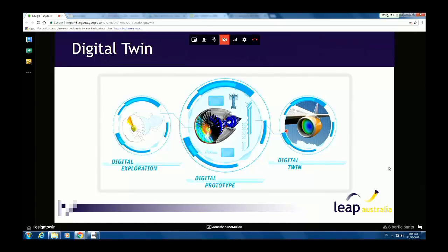Depending on how complicated the digital twin is, it can do things like fatigue calculations. So it will throw a red flag if the vibration is causing the design life of your bearings to drop too far. And so particularly for automotive models now, where the design isn't actually too complicated, this is very, very useful for looking at a system which you can't actually touch. So if it's mid-race or a UAV is in mid-flight, you can pull up your digital twin and use it to start checking whether what it's doing is sensible, and where you need to do service.